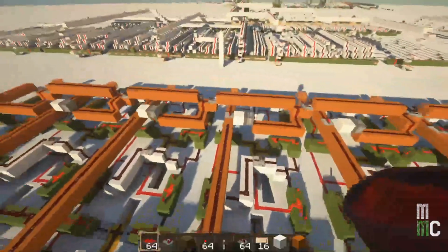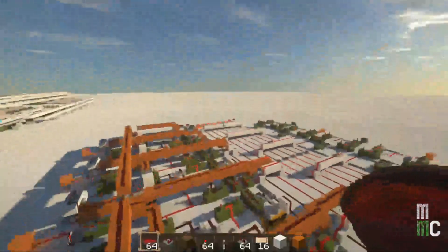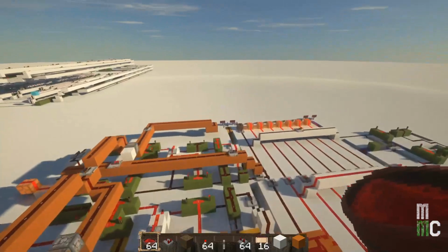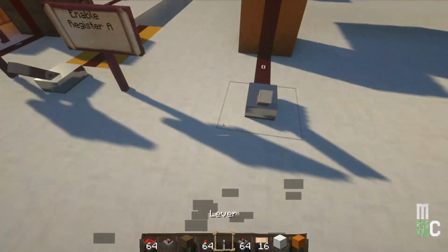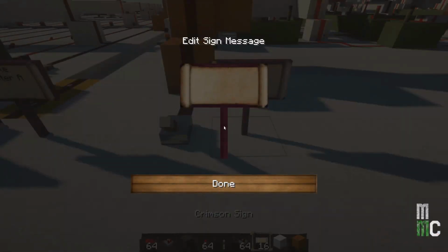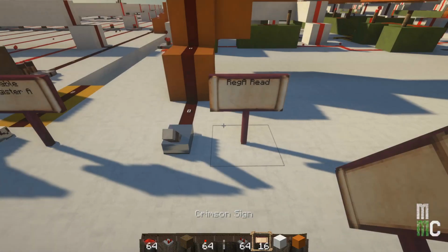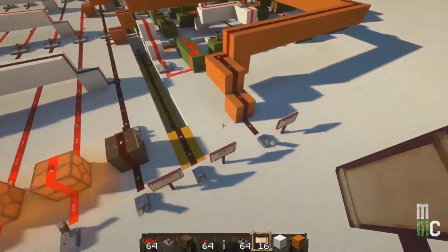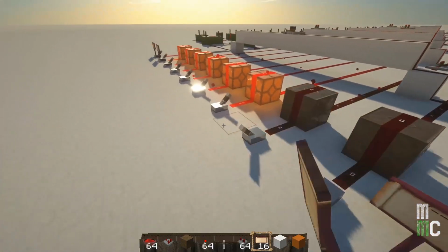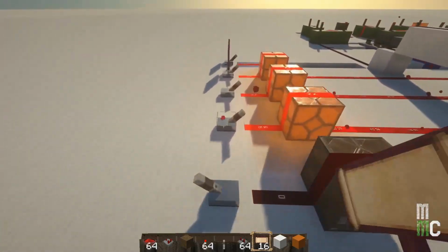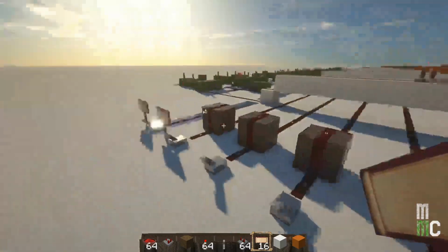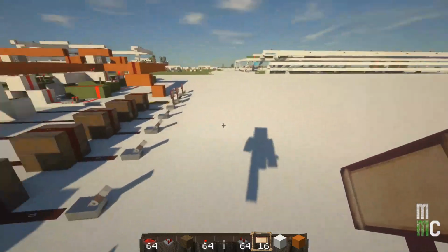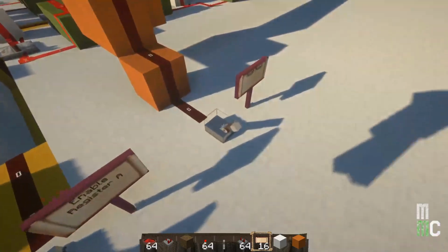With all these bits on, we now enable the output of the register, which is this switch right here. We're going to call this a read, and turn it on. Turn all of these off. So we have nothing on the bus. Got the enable off too, awesome. And then we turn this on.